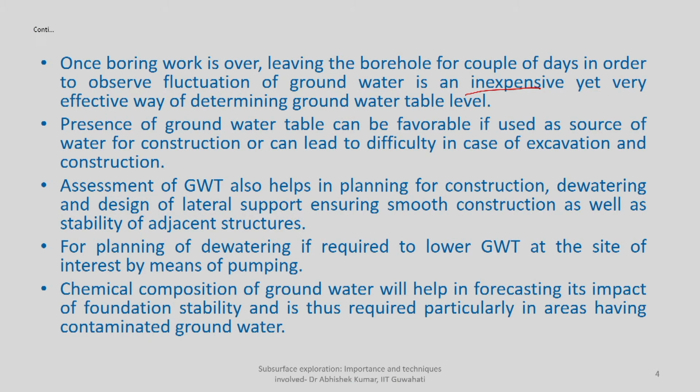Or you can go for dewatering or design of lateral support, or you can go for dewatering by means of some kind of pumping. So, whatever water is coming at the side, you pump it out onto some other impermeable layer, so that the water can be drained out quickly, at least for the time being, when some kind of concrete laying or some exploration work is going on. Because after that, by the time the water table starts gaining its original position, your impervious layer will be there at the site. That will ensure there will not be any further problem because of shallow groundwater table.